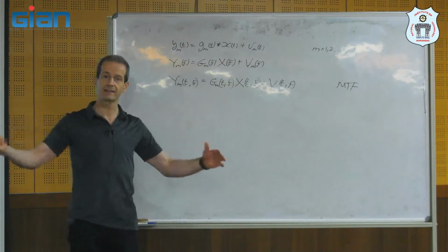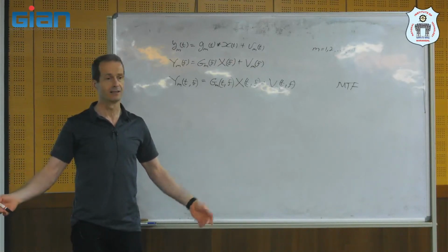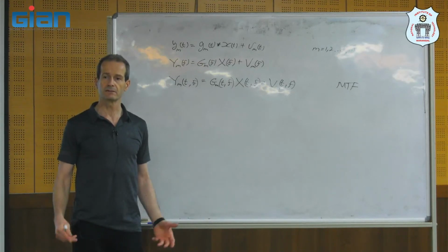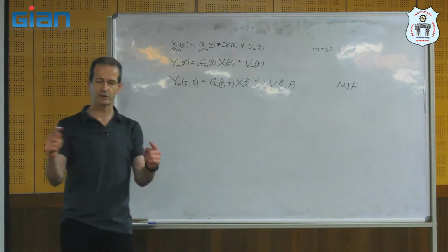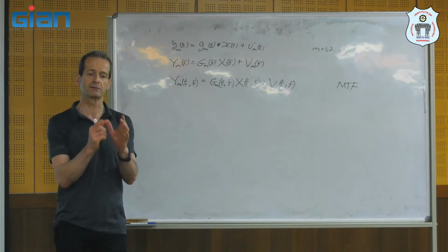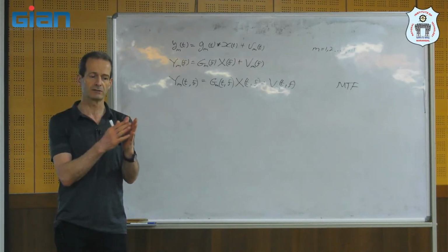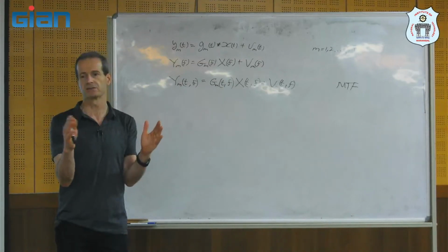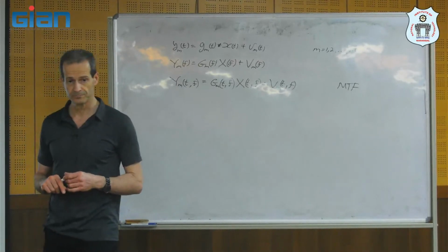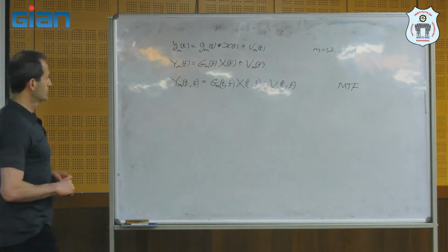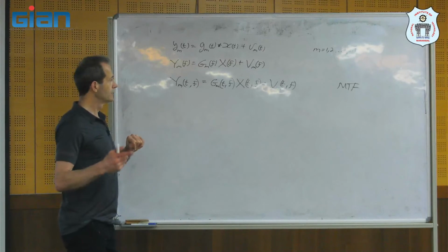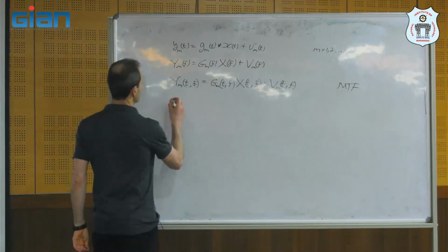Of course, we can take a longer window of the STFT, but this has a very big disadvantage, because then during that window we cannot discriminate or identify different phonemes or different parts of the speech, because during that window the signal is non-stationary, it is changing during hundreds of milliseconds. So what do we do? Okay? So instead of coming from here to here, you see, we need to do something else.